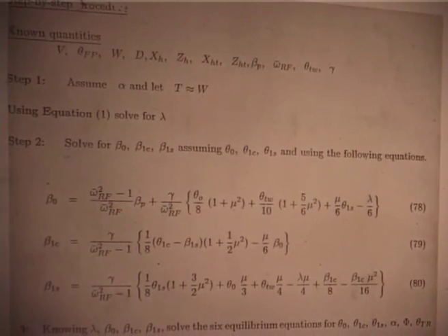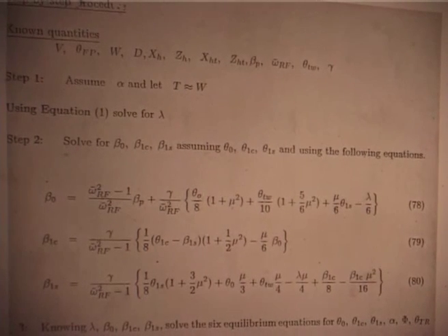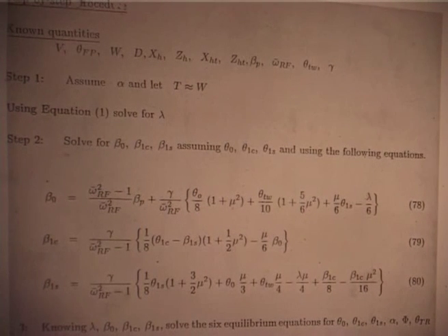Now, how do you start? Because it is an iterative procedure, you do not know the inflow. So first you assume thrust is equal to weight, and always start this analysis from the hover case. Do not straight away start solving at mu 0.3, because sometimes it will not converge. So, you start from hover, which is the simplest case, you take those equilibrium quantities and then slightly change them, then go to the next forward speed, which is mu 0.05.